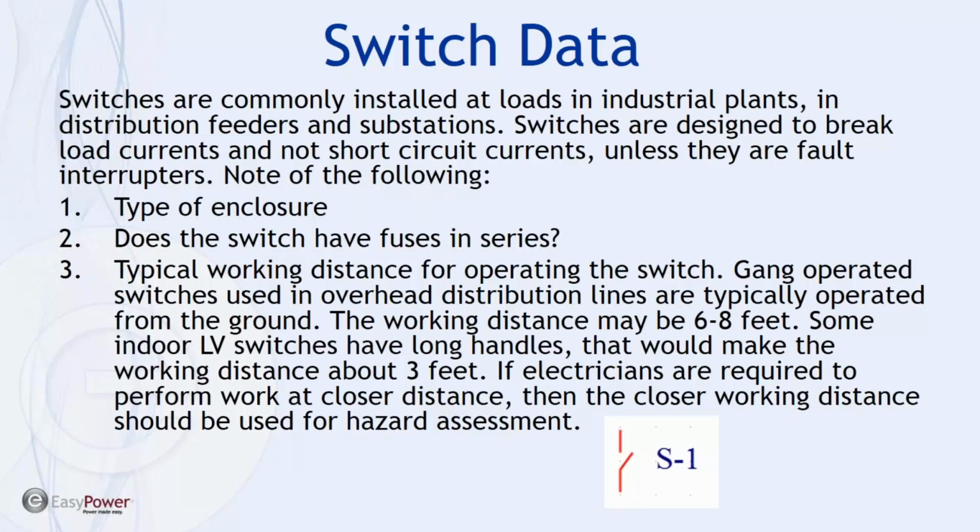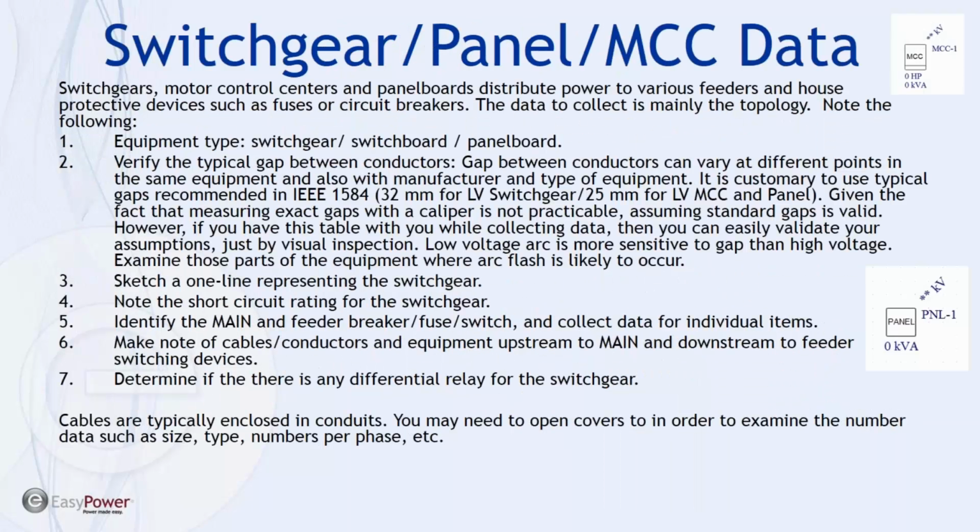Switches are commonly installed at loads, and in older buildings there may not have been a protective device or a fuse installed. Make sure that you understand what your installation is, if there is a switch with a fuse, and the details on both the switch and the fuses, because if there's not an adequate localized protective device, this could be an extremely dangerous setting for an arc flash situation.